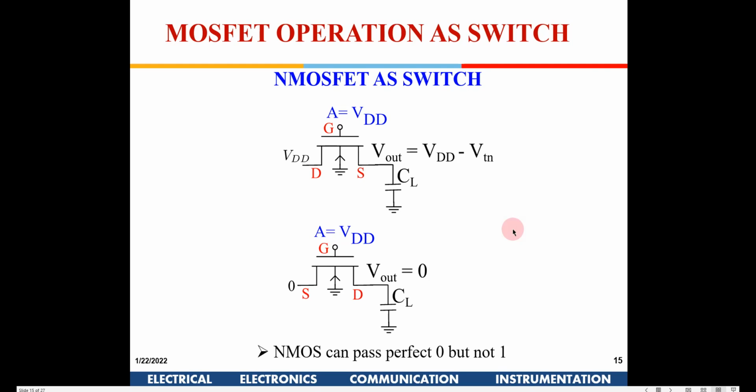When you pick up a device even in Cadence or any software, drain and source will be written there, but they are symmetric and interchangeable. You don't have to make these changes here. The way the current flows in these devices defines whether it is a source or a drain, not the alphabets written there. They are merely labels for easy understanding. What makes them source and drain is the way you connect it.